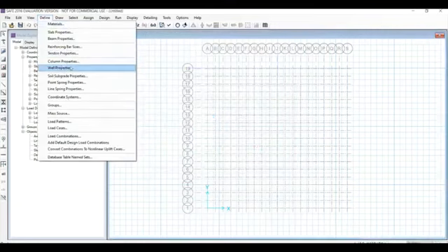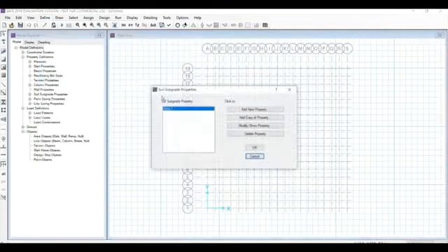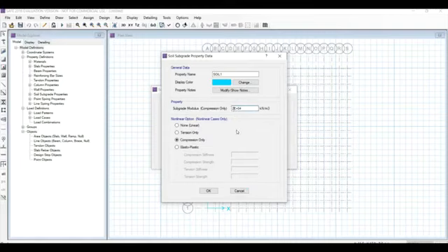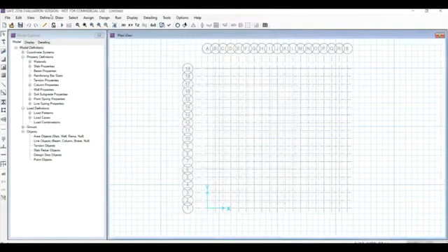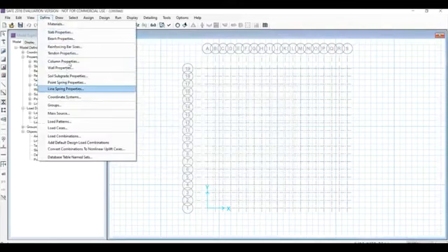And now define the soil subgrade properties. Let us assume about 30,000 for the soil subgrade, and modify the soil subgrade property. Here we have 20,000, so make it 30,000 by changing it here to a 3, and then click OK. Click OK, and then the column properties and the soil subgrade properties are completed.